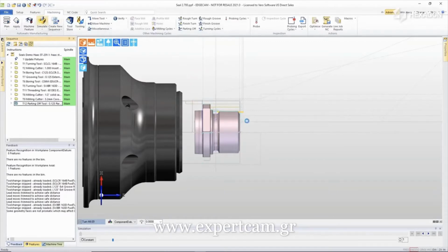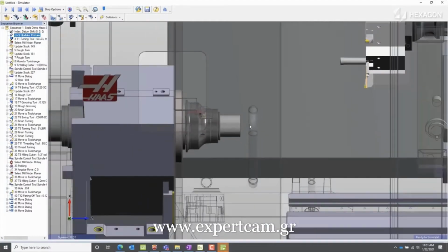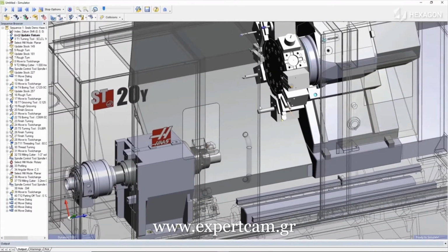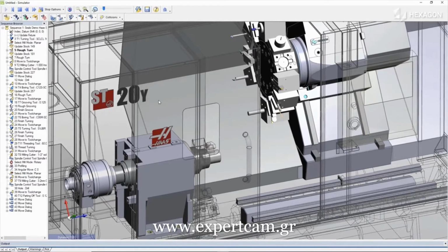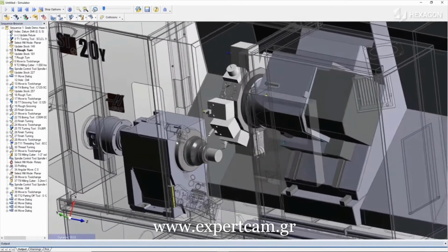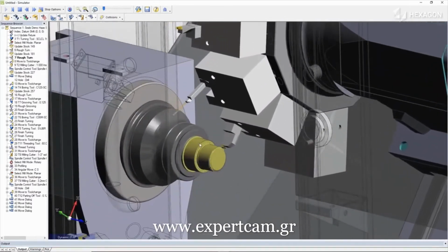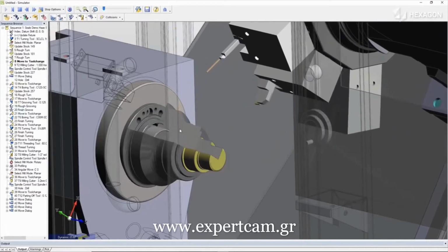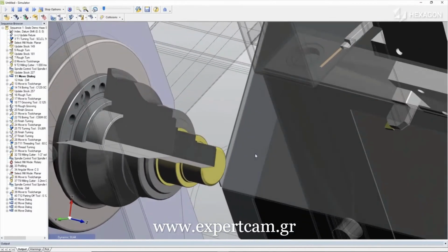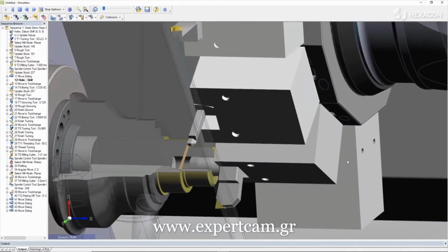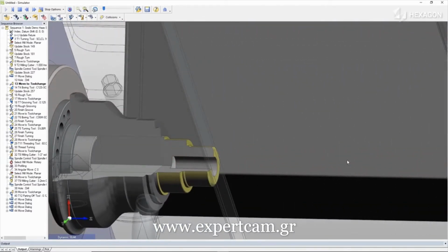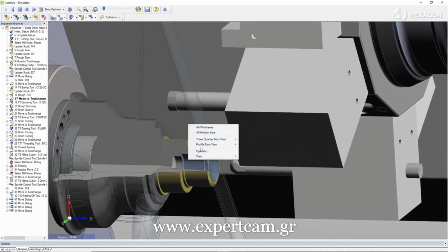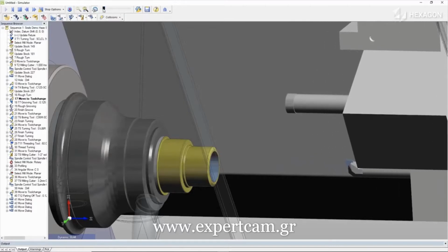Let's look at machining simulation, where we can see how this setup works. Notice that the part begins as a blank of material. We can see the CNC machine and all tools in the turret. Everything in here is collision checked, and we can see the machining simulation and how the material is removed from the part. We have the ability to cut away the inside detail, which can be helpful for seeing tools such as our drills and boring bars and ensuring that our process comes together correctly and without problems as we intended.